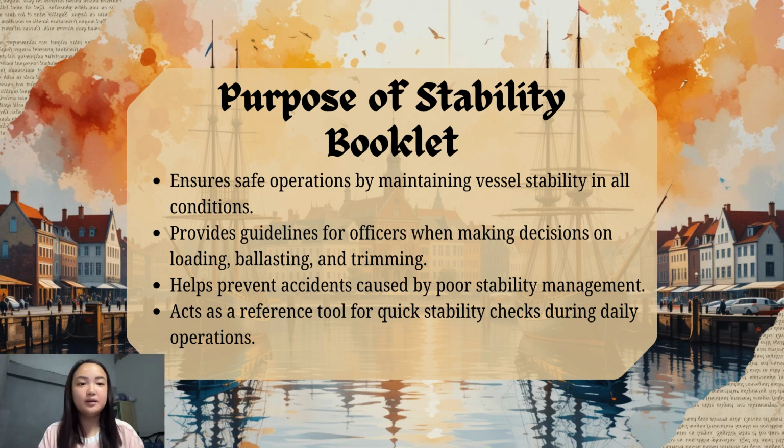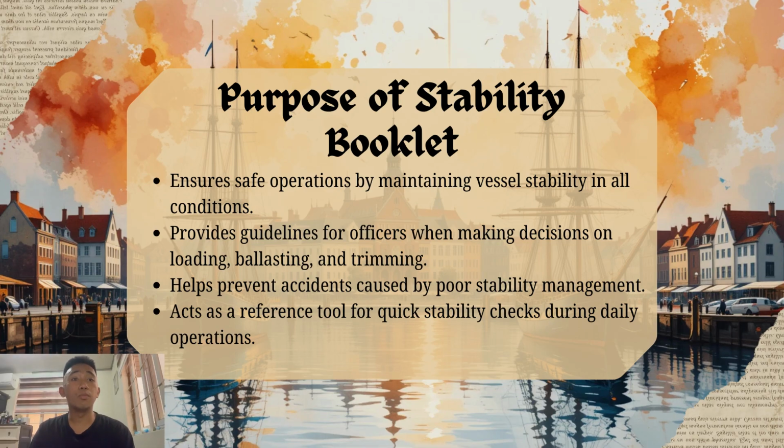Hello guys, I am Danica S. from BSMT 3 Alpha. I will explain the stability information purpose. Purpose of the stability booklet: ensure safe operation by maintaining vessel stability in all conditions. Provide guidelines for officers when making decisions on loading, ballasting, and trimming. Helps prevent accidents caused by poor stability management. Act as a reference tool for quick stability checks during daily operations.